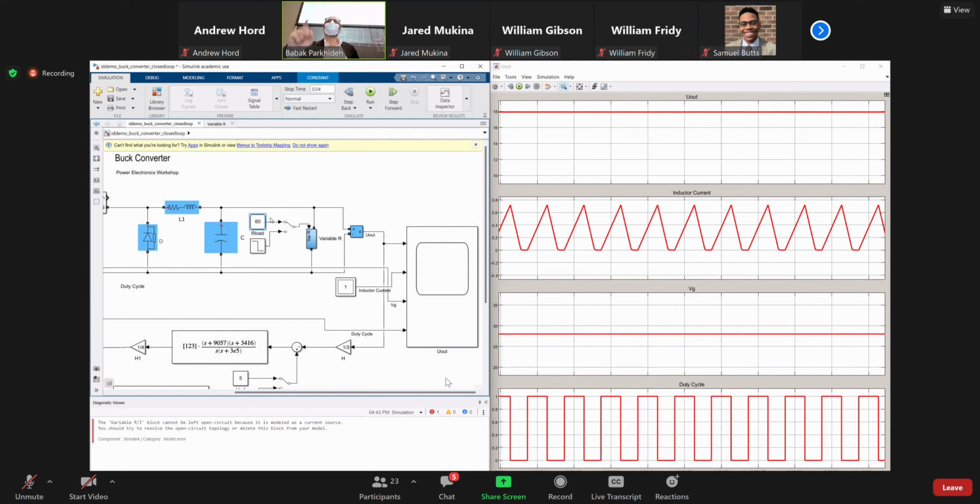If that omega, or the resonant frequency, is close to the switching frequency, and if you do not have any active load, then your buck converter behaves like a boost converter. It shoots up. So there are some applications.